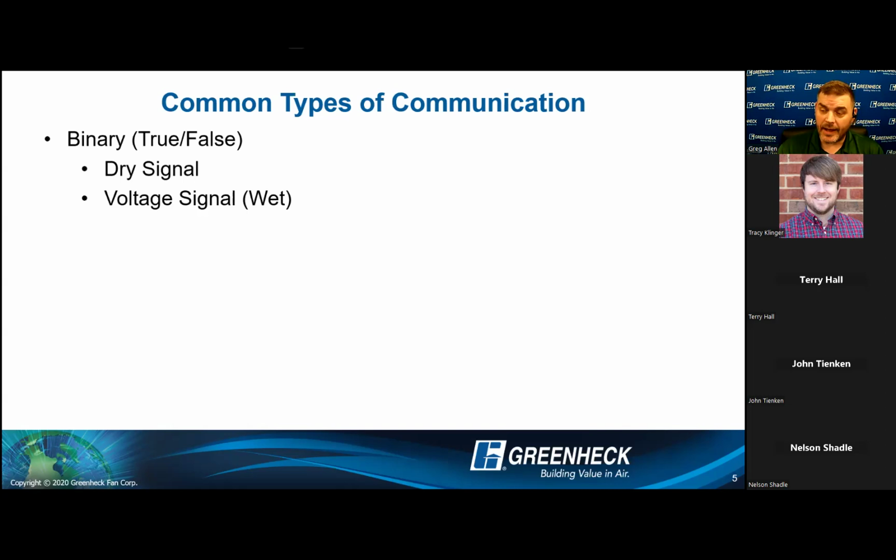But if you didn't catch that, this is one of those things that's going to take a couple of days, get some parts in, maybe a transformer, and you're making a translator at that point to convert one signal to another. The other thing I want to say about the dry side is, let's say I'm that carbon monoxide detector again, and I'm just closing a contact. Well, if my receiver is speaking dry, that's great. We're done. Two wires. It's a complete circuit. It's a broken circuit.